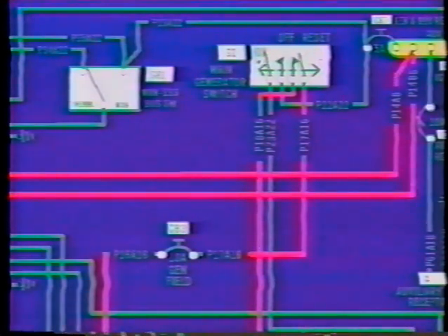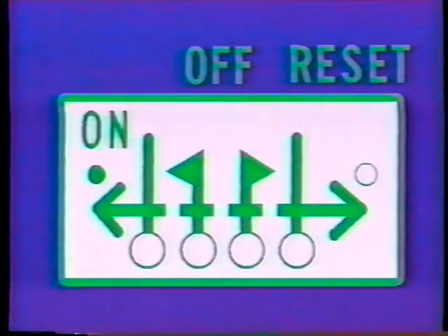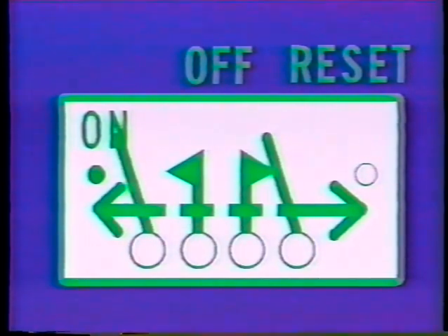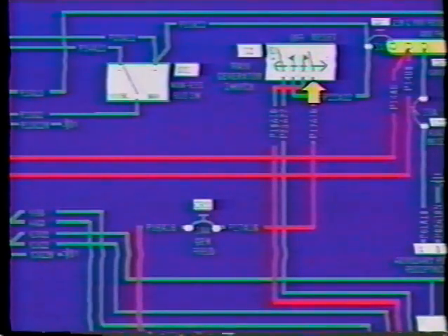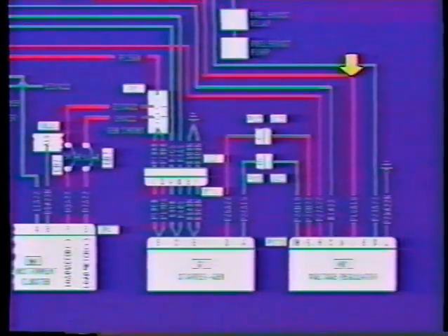The generator switch is a single-throw, double-pole switch. Looking at the switch, the flipper on the left will displace to the on position. At the same time, the flipper on the right will follow. This action will allow the awaiting unregulated voltage to move through the generator switch to pin J at the voltage regulator. For the first time, the voltage regulator has an opportunity to sample the voltage being produced by the generator.